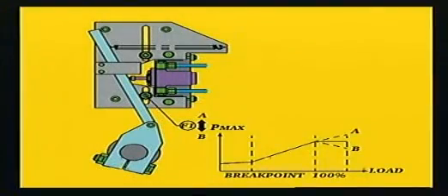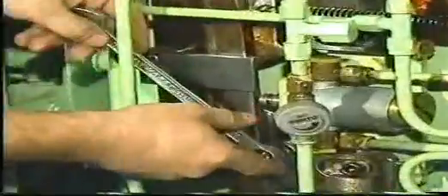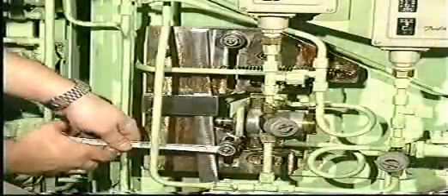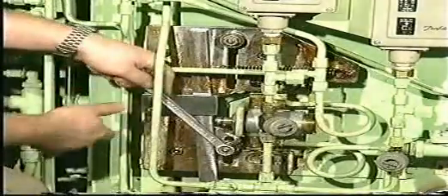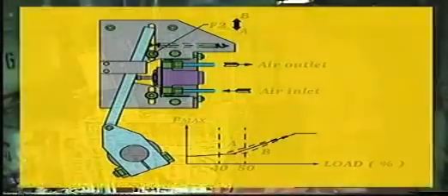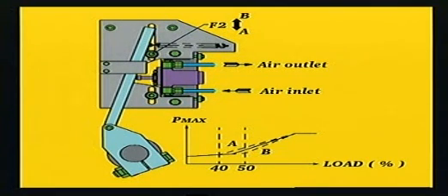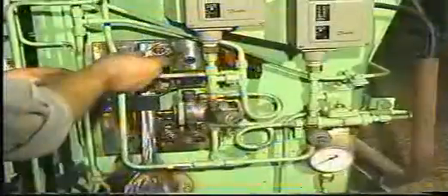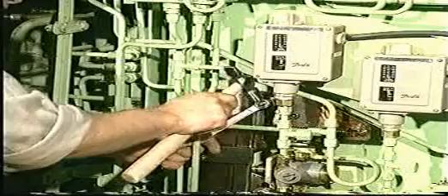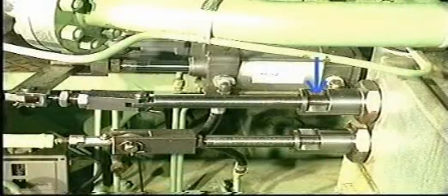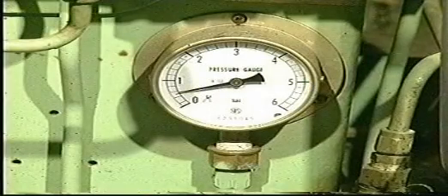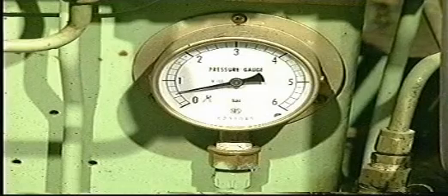Load the engine so that it corresponds to 100% MCR load and displace the lowermost pivoting point until the average combustion pressure, corrected to ISO ambient conditions, is at the required value. Increase the load until it corresponds to 40 to 50% MCR load and displace the uppermost pivoting point until the VIT racks just start to move inwards. This occurs at a control air pressure of about 0.5 bar. Lock the pivoting point in this position and change over to normal engine control.